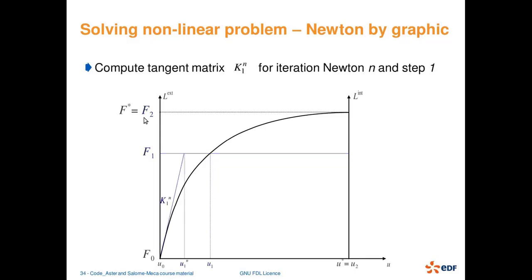Now for that purpose, we first compute the tangent matrix at the previous time step, that is f0 or t0, and applying that tangent matrix and this force, I get the incremental deformation at this iteration.